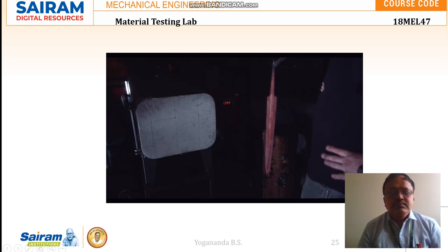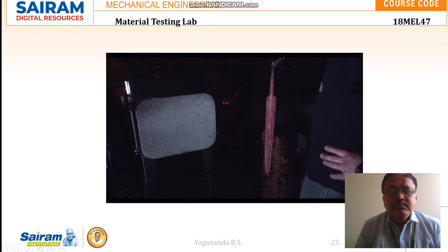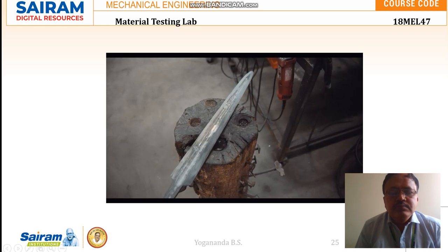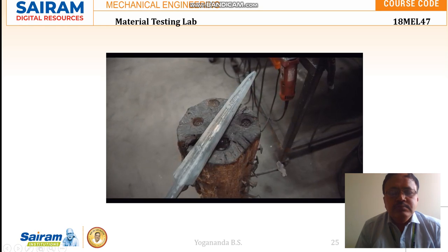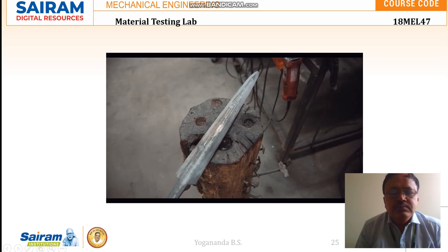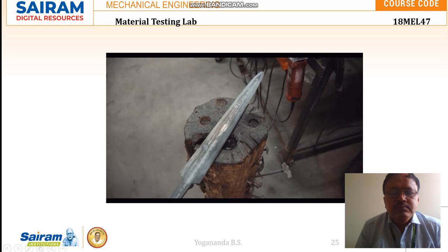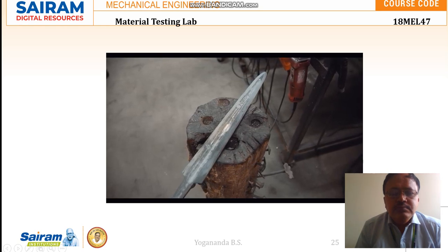The next step after normalizing is hardening the blade. Steel can only be hardened when it has enough carbon content. Generally, the more carbon, the harder you can make the steel. As I had mentioned before, steel is in crystal form, and the position of the carbon in the iron matrix determines the hardness of the steel. There are 3 carbon arrangements you should be aware of: ferrite, which is soft, martensite, which is hard, and austenite, which is the carbon arrangement when the steel is at critical temperature. When working with pattern welded steel, the pattern becomes visible under heat due to color differences and oxidization, as you can see for the sword here.